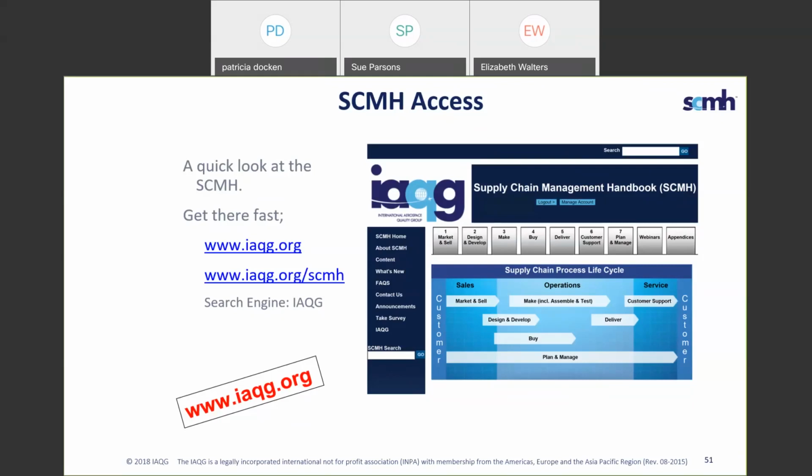Was the question about the characteristic ID column? Is that what it was kind of asking about? That typically will come if it's identified from the DFMEA or the process flow or the PFMEA. There might be an ID type number that you'd want to carry through to show that linkage between the different artifacts. I have to be honest and say I haven't seen that used as much, but there is a column there to establish that if it helps with the linkage.